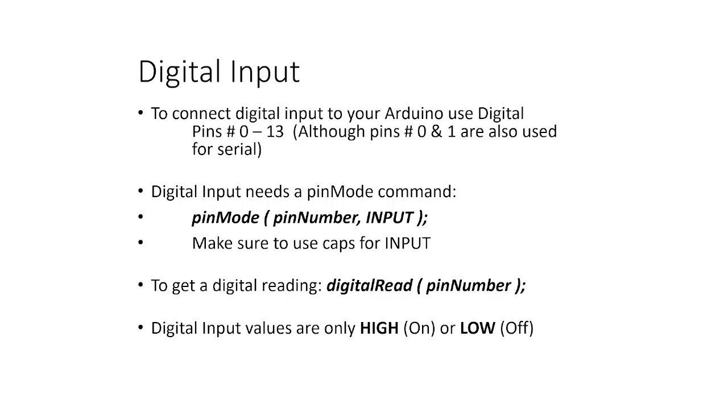After uploading the code, you can then use pins 0 and 1. Maybe you should avoid connecting your components to pins 0 and 1, in case you need to change anything in the code and re-upload it.